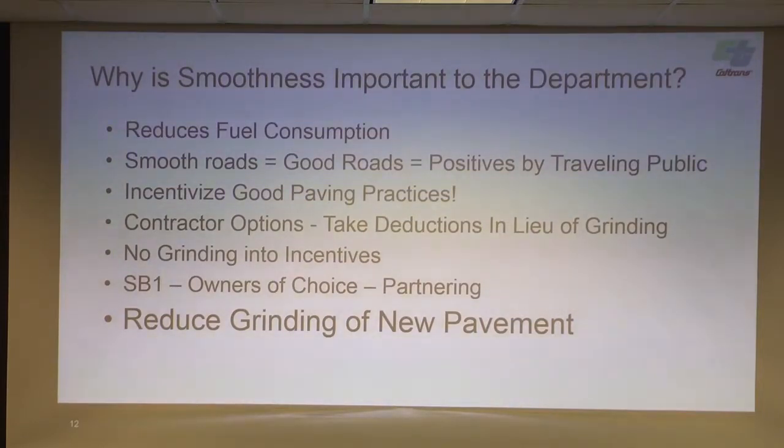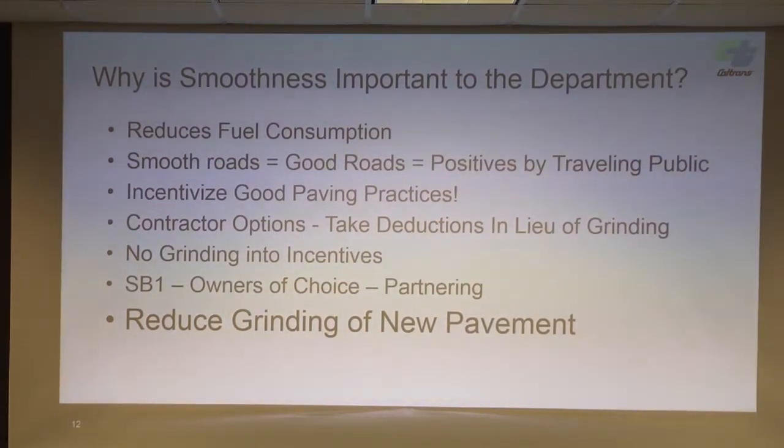Why are we doing this? Why is smoothness important to the department? It reduces fuel consumption, so it helps with greenhouse gas. We want to incentivize good paving practices, and that's important because we want to reward good paving, and we want to give contractors the option to take deductions in lieu of grinding. We don't want them to grind into incentives. So we don't want them to put incentive money out there and grind to get the incentive. So we're not allowing that in the spec.